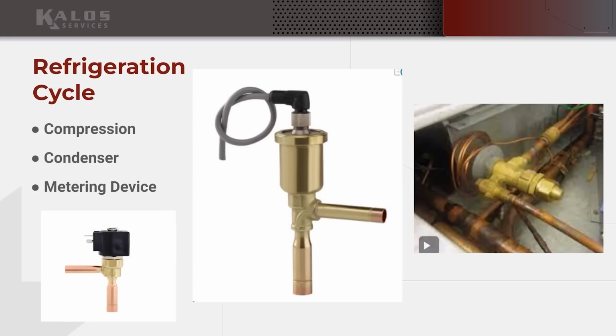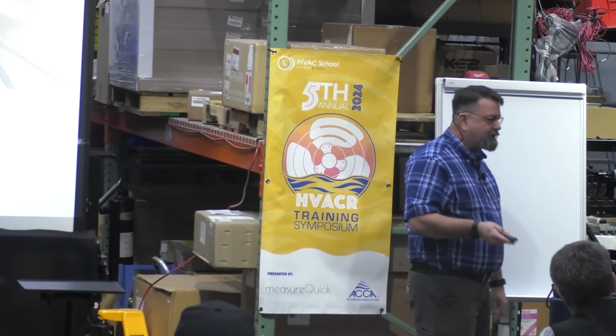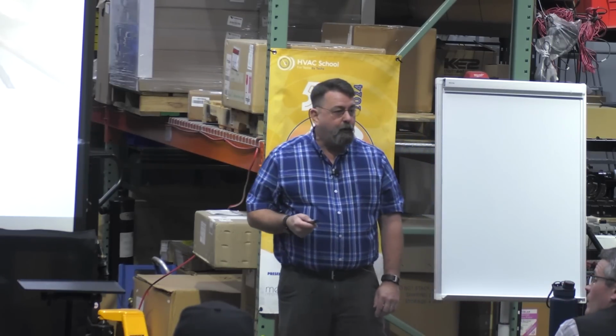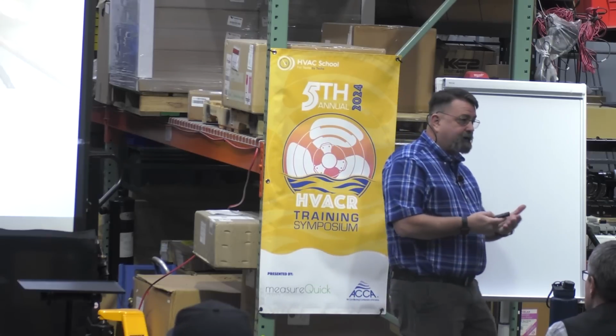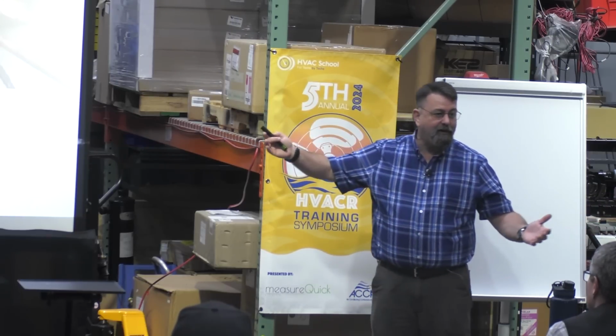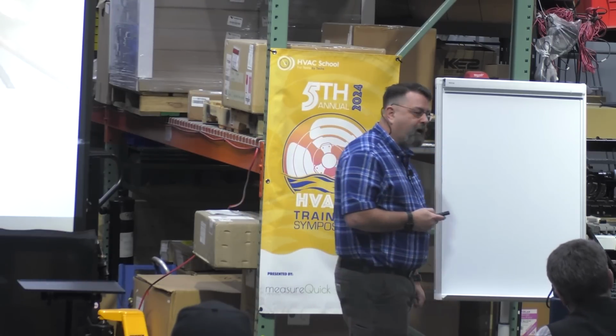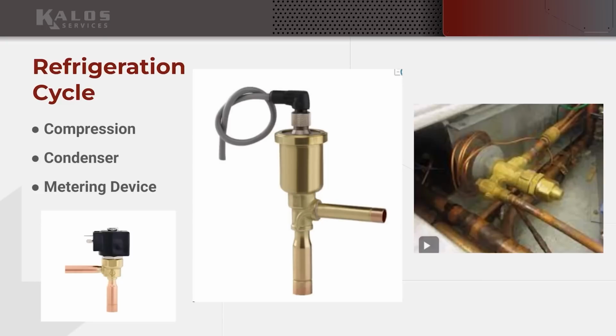We've got a strainer to keep it clean. We've got a nut we can take off there and a stem we can adjust. Right? That's kind of standard. Now, not all of them are that way, but that's kind of the standard because our system is so big, we can easily get some debris in that system. And I told you I'm going to have 40-some cases, right? That means I could damage 40 TXVs, so I'm probably going to throw a strainer or something in there to catch that, right? And then the other thing is I've got to tune that evaporator exactly, the amount of airflow that's flowing through it to match the refrigerant flow.